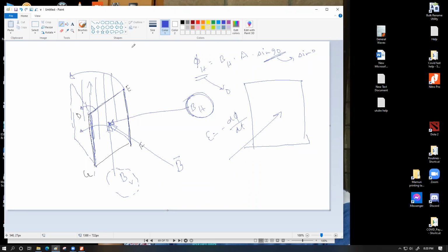So sir, for the vertical component, EMF is produced only in EF and DG, right? For the vertical component, we are having equal EMF produced across D and GF because the D part and GF part are actually cutting across the vertical lines. And EF is not producing EMF because it is always remaining parallel. Exactly. So for the last question we could give EF and DG as the answer. I would appreciate that one as the most correct answer. If you connect a voltmeter across these two sides, you definitely get it.